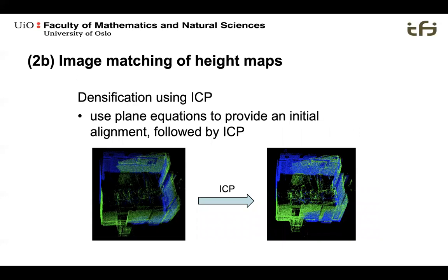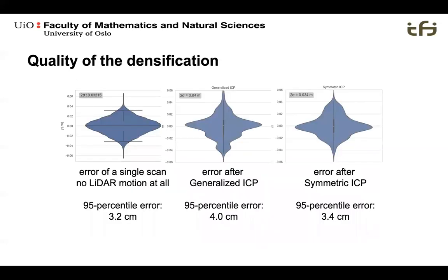And here we see how that ends up. We have the point clouds for the two different scans on the left side. They're coarsely aligned. We are running another symmetric ICP or generalized ICP. And on the right side, we have the resulting matched point cloud, which again doesn't end up in wrong local minima because we have a very good prior.